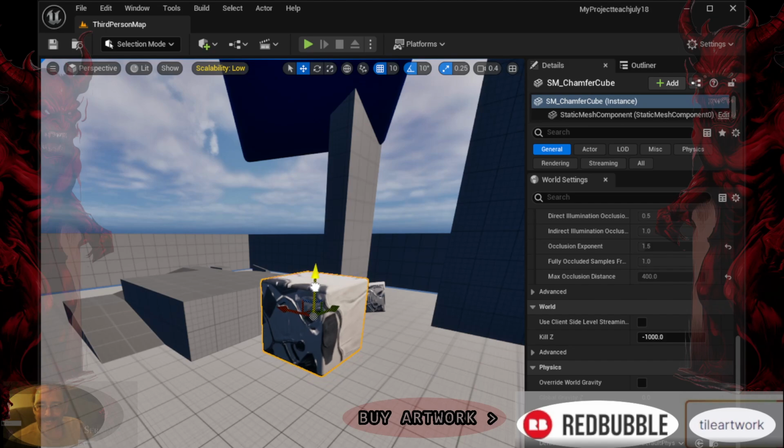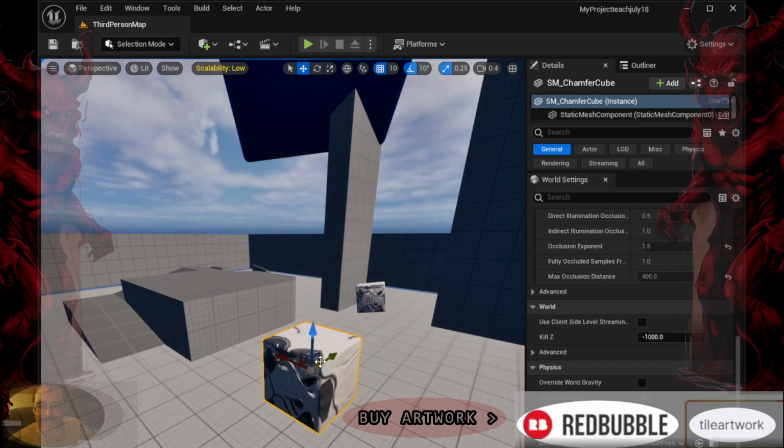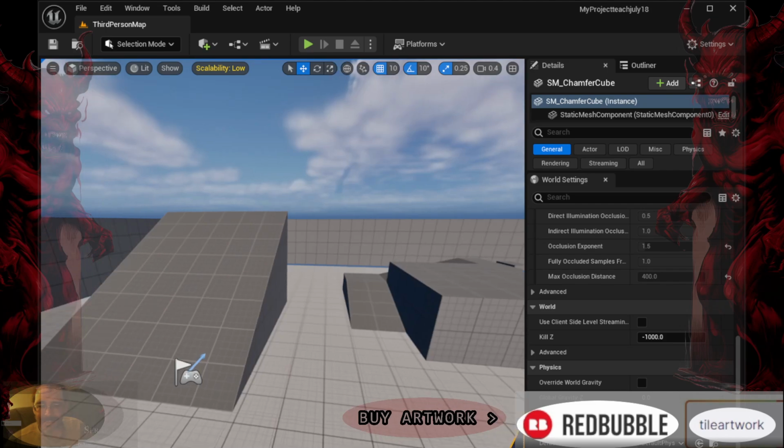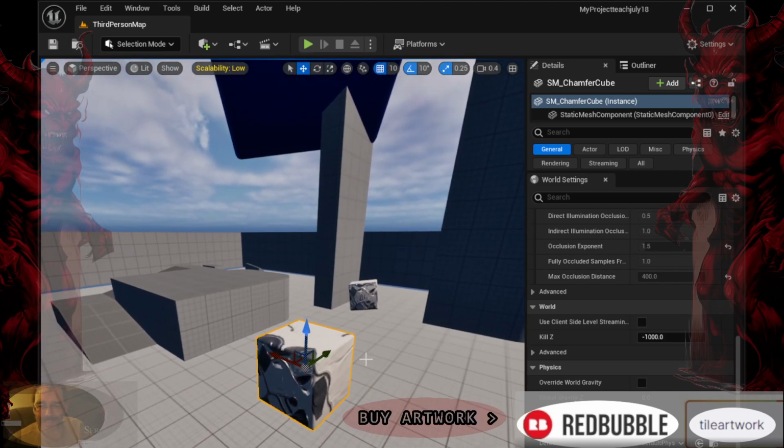Keyboard input. Alternatively, you can input precise movement values directly into the transform fields in the Details panel, or use keyboard shortcuts to nudge the object in specific directions. 3. Precision and control. The Move Mesh tool provides precise control over the translation of mesh objects, allowing you to position them accurately within your scene. This is essential for aligning objects, adjusting their placement relative to other scene elements, or setting up specific layouts and compositions.